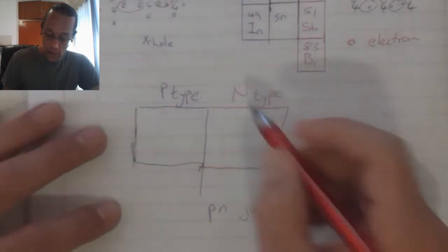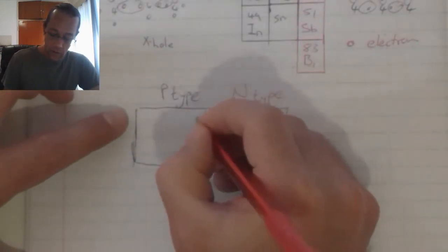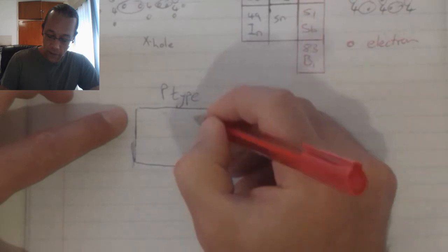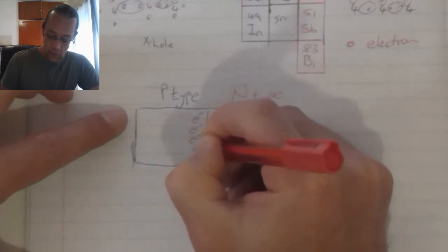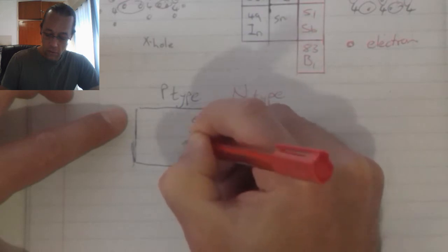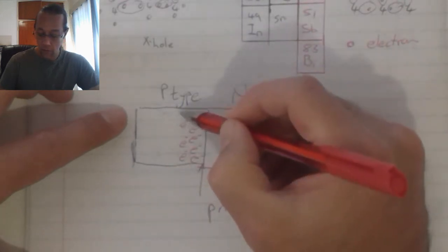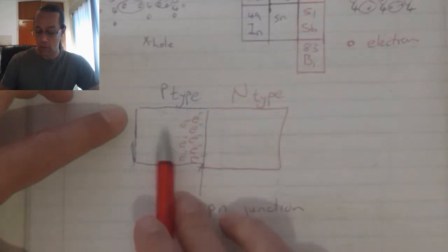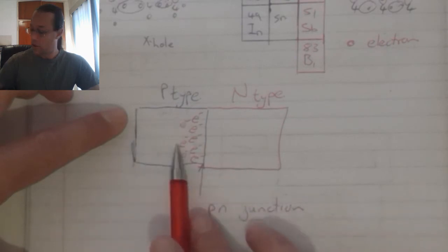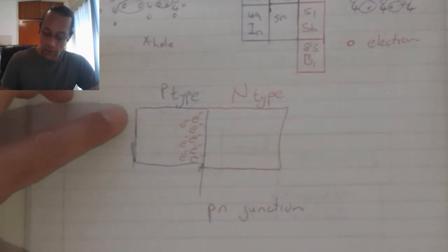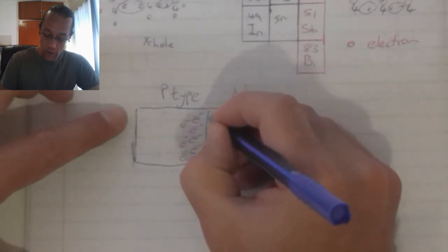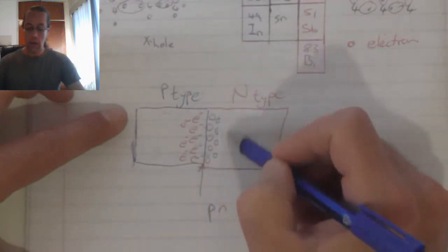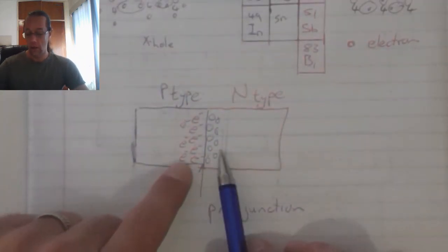And what we then find is in the N-type material, on this edge of my PN junction, we will build up a layer of electrons that will form sort of a barrier that pushes electrons away this way and pulls holes into this side. And then what we find in the P-type material is we have a buildup of holes, which again forms a barrier within the N-type material.